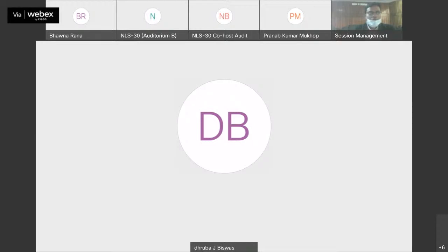Yes, yes. So in case of Gaussian beam, we all know that it is well exploited. It has a full width half maximum and it has a Gaussian profile. But in case of Bessel beam, the interesting part, which I have shown in my second slide, is that it has a central lobe where it is depositing the maximum energy. The rest of the energy is deposited in terms of concentric rings, which creates interference when you do a raster scan. It's kind of interference of two Bessel beam induced ablation waves propagating on the substrate.